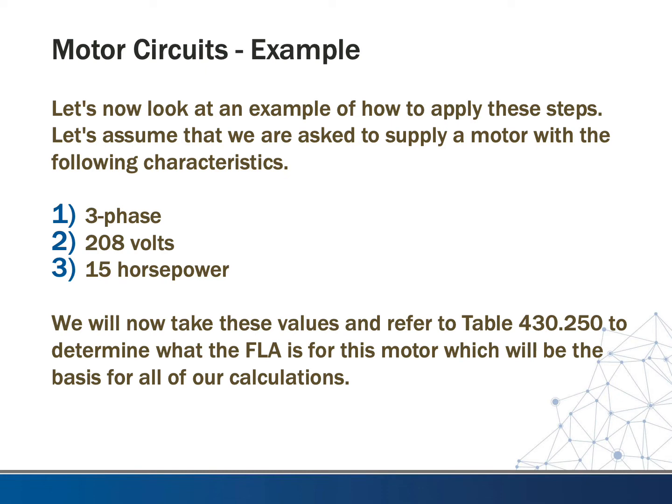So we will now take these values and refer to table 430.250. Remember, 430.250 is for three-phase, 430.248 is for single-phase, so 250 is the one we need to determine the full load amps for this motor, and that's what we're going to use to start our calculations.